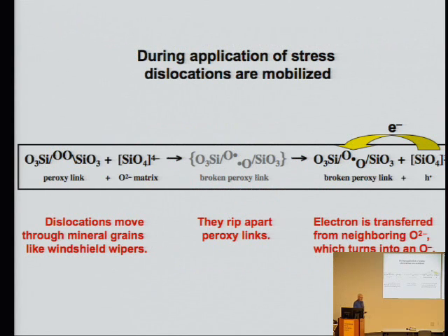And indeed, when we, instead of heating, choose mechanical stress, if we have mechanical stress, shear stresses, we are generating dislocations. The dislocations are sweeping through the crystal structure in huge numbers. A cubic centimeter of material that becomes moderately deformed produces enough dislocations that if you would put them end on end, you would be able to run to the moon and back from one little cubic centimeter. So efficient is this process of dislocation generation during mechanical deformation.